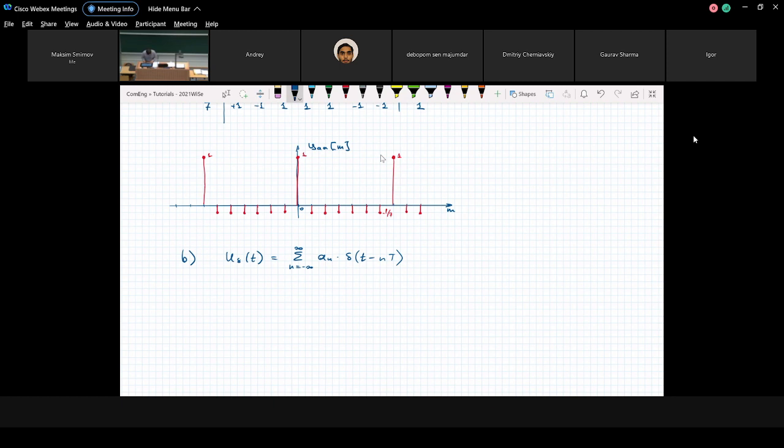And then when we plot it, I just repeat this plot, but instead of each discrete pulse, I put a delta pulse. The original amplitude was 1, but for this resulting autocorrelation function, I put 1 over capital T. I also normalize by the spacing between delta pulses.